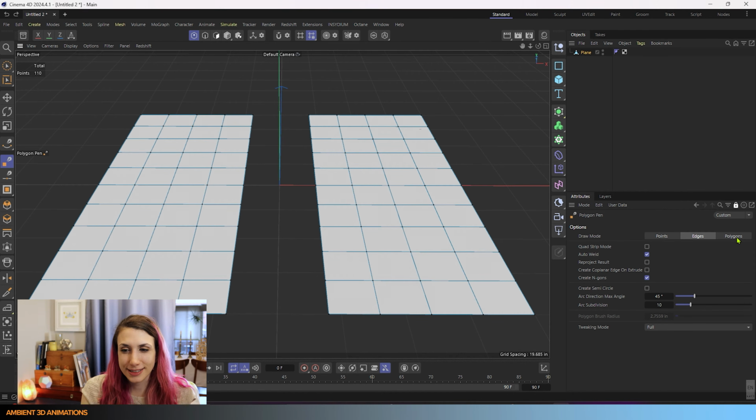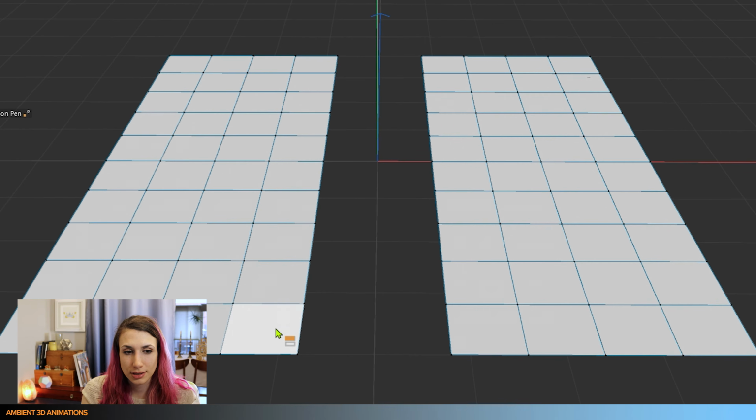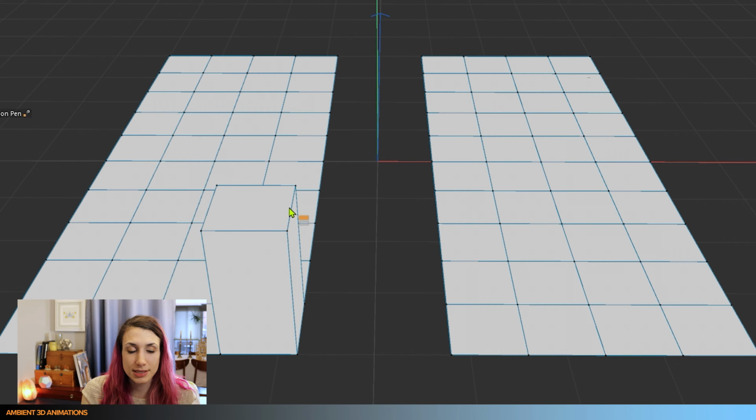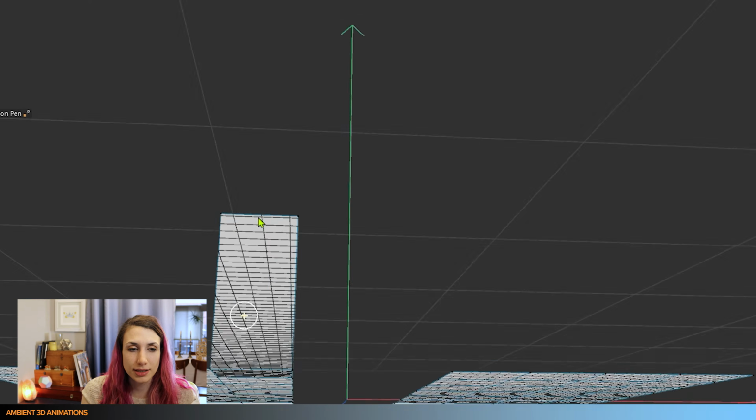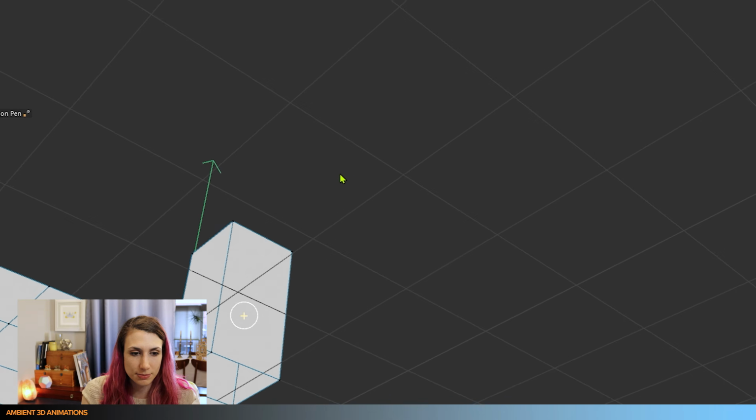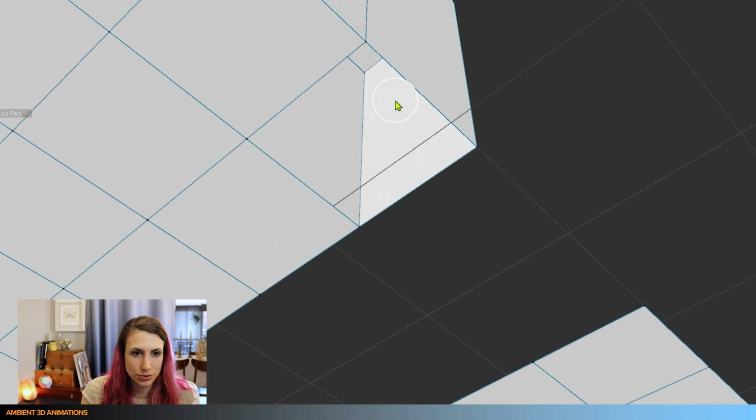Now there's some interesting things you can do with polygons, which are rather fun. So let's go back over to here. I'm going to click on this polygon, holding Control. So we're clicking and holding Control, and we're going to drag up. From the center of the polygon, we are extruding, so this may remind you of the extrude tool.